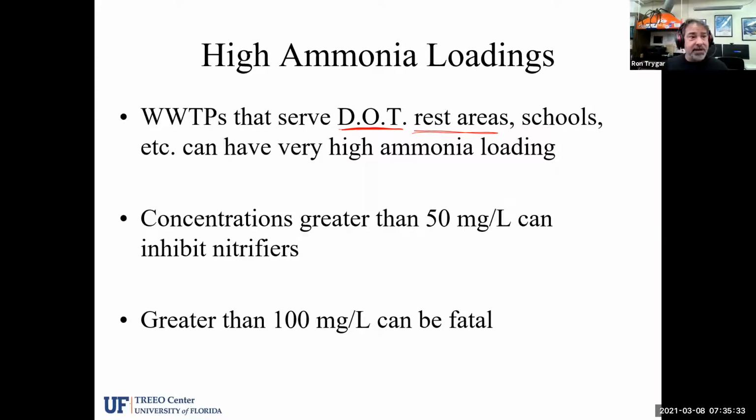We're also finding many people now elect to use and build these facilities with low flow toilets or zero flow toilets, which means that the urine itself is what's moving the waste through the pipeline, and so it's becoming more concentrated. So the urine, the urea entering the treatment plant with the organic nitrogen is more concentrated than before. So we could see a definite load coming into the plant that places a high demand on our oxygen, our dissolved oxygen, and our aeration equipment.